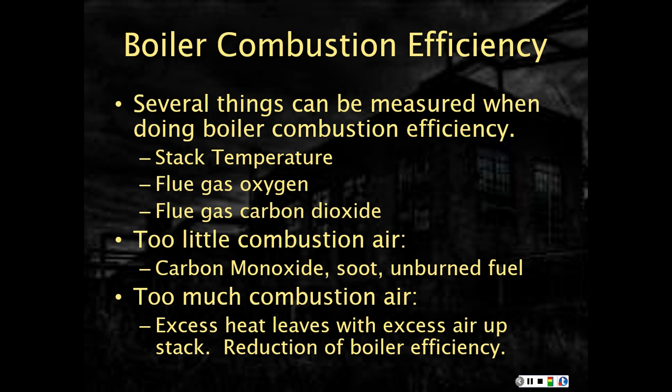Now, too much combustion air. Like we mentioned before, with too much combustion air, excessive heat leaves with the excess air up the stack, and again we have a reduction in boiler efficiency. Now if we go back to too little combustion air, it's obvious why making carbon monoxide is a bad idea. Now the soot, if we start depositing soot on heat exchanger surfaces, we also reduce the efficiency or the heat transfer rate of the heat exchanger. So either condition is not good and adversely impacts the efficiency of a boiler.